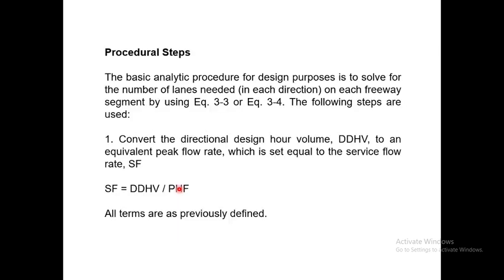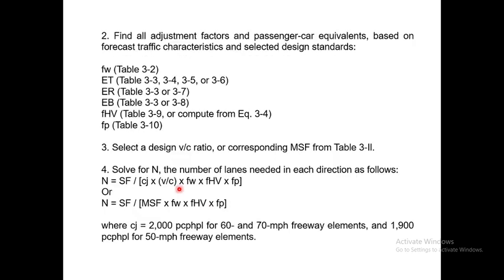So as I mentioned, the first step is just to convert all the volume to the SF. Why do we do this? Because we need a 15-minute rate, volume rate. So first of all, SF. Then again, all the factors: factor for lane width, factor for heavy vehicles, I mean trucks, and last is the factor for population.